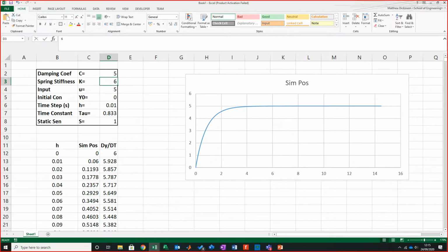So if I almost match it to achieve almost critical damping completely, and I go something as, I don't know, let's go 5.1. What we're really getting now on this response, the settle time on it is 6, apologies, that's my phone for eBay. Now we're taking 6 seconds to reach a steady state. However, that time it moves, that distance it moves, and the way it moves is very slow.